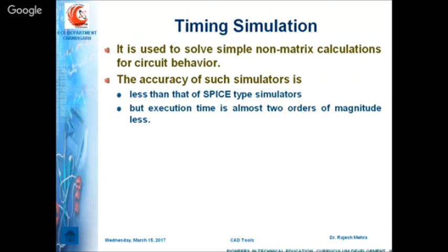If there are 10 AND gates, then the delay of the circuit will be 20. Here we are not actually calculating the RC delay, meaning we are not considering simulation at transistor level. We are just calculating an approximate idea of delay, unit delay, based on the number of gates available. Each and every gate is going to give you some unit delay. Maybe an inverter can be calculated as 1, and an XOR gate as 2. So based on the number of gates available in the design, you get an approximation, meaning approximately how much delay will be there in your design. But for accurate time delay, you have to go for SPICE simulation at circuit level.